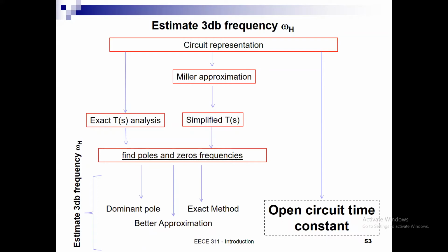What this does is it handles things one at a time, one capacitor at a time. It assumes that starting from the original circuit, I'm going to add one capacitor at a time and see what is the resistance that it sees. Let us see how this works.